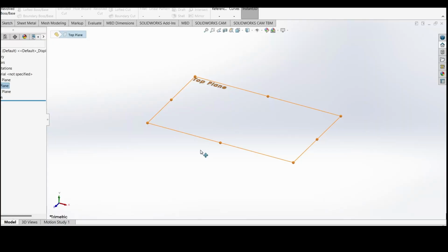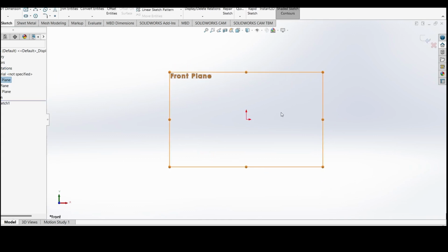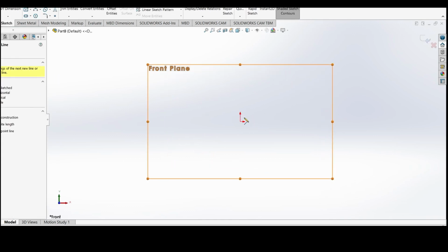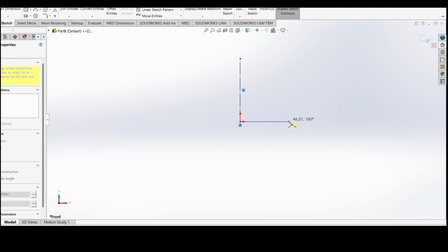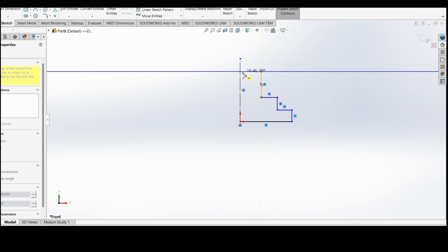Alright, so now we're here in SolidWorks, and these round features are calling out to me, and they're saying revolve. Whenever we start revolve, I like to start with a center line. I'll come around and dimension it. Now here's a trick. The measures we took were measures of diameter.